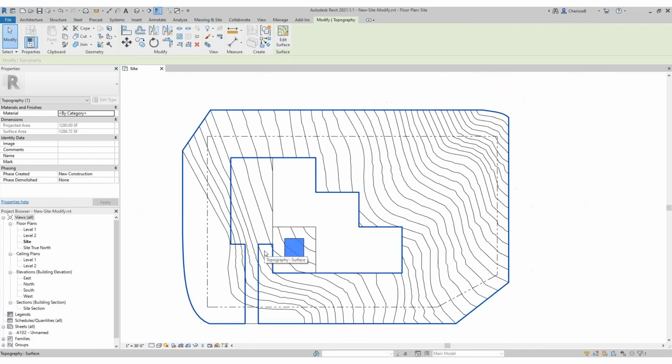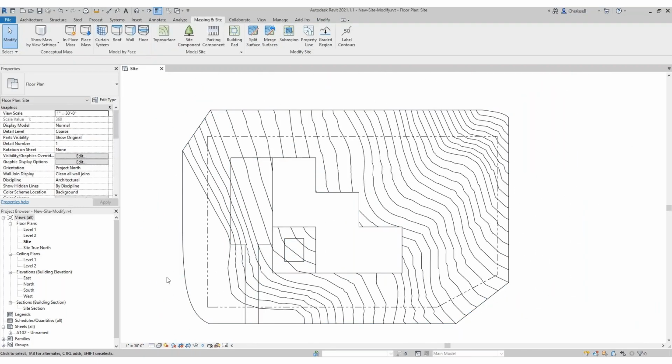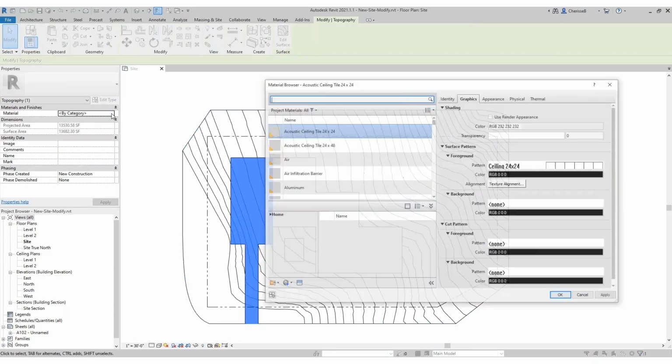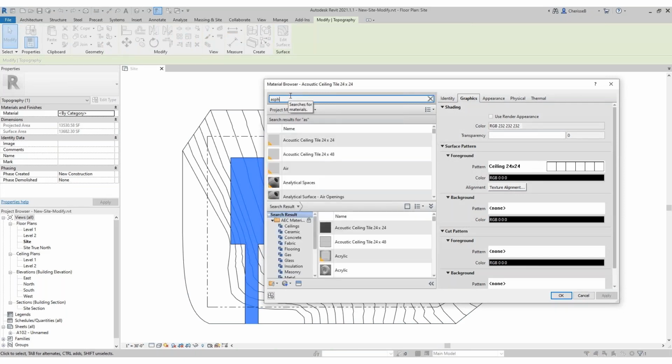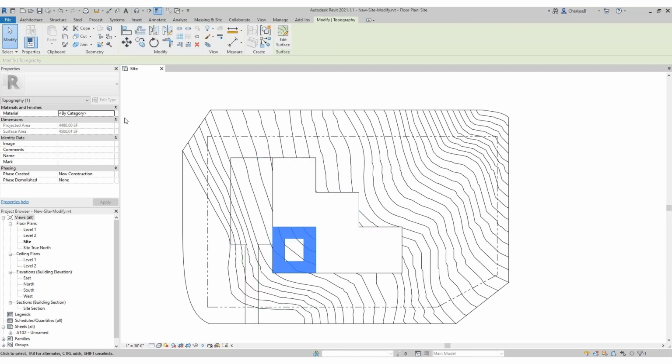And the next steps in practice 2C is setting the materials. Now, in these steps, I have you find the material, add it to the material list, and then check the use render appearance.